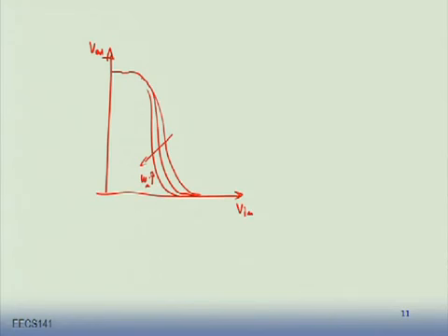How do you find, for one of these curves, what are the noise margins? I need to find what is V input low and V output low, V input high, right? These are the gain of 1 points. How do you do that? It looks like I would not be able to get away from what Rachel has suggested: solve this analytically. Find what is the mode of operation over here and solve it analytically, then differentiate, equate that with -1 and be done with it, right?